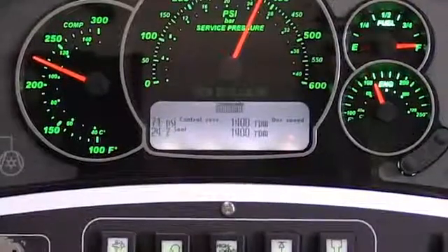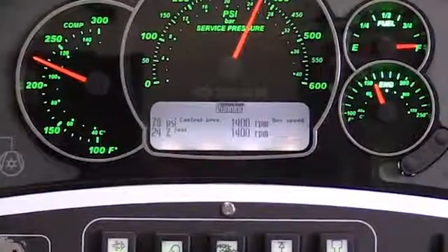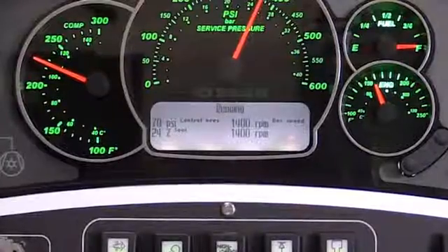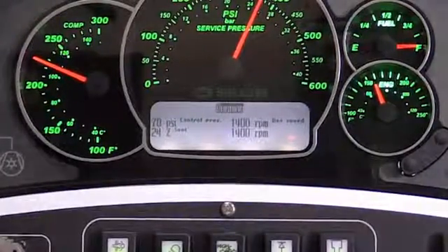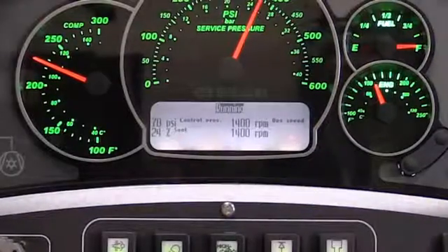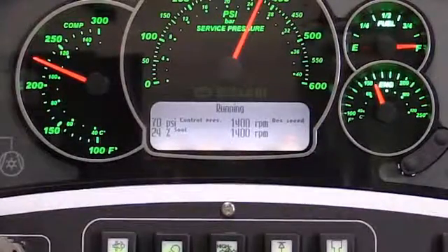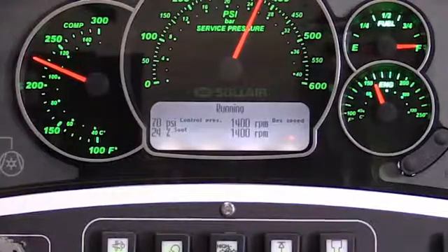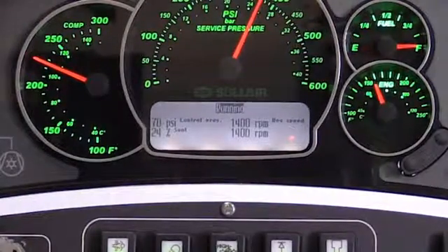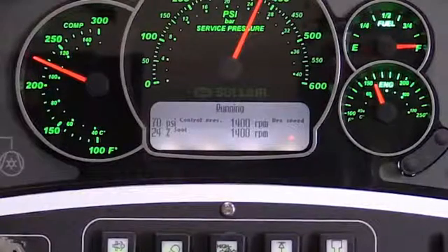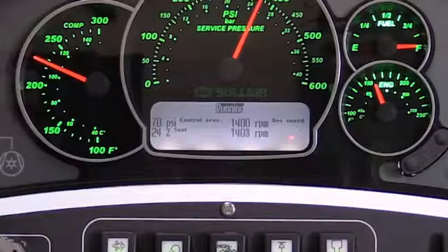What we'd like to demonstrate for you now is the 3 modes of operation: unloaded, modulated, and loaded. Monitoring control pressure is the best way to tell whether you're fully loaded or not. The exact point you reach 0 of control pressure while loading the machine is the point where you're going to be fully loaded. So I'm going to bring that up on the display.